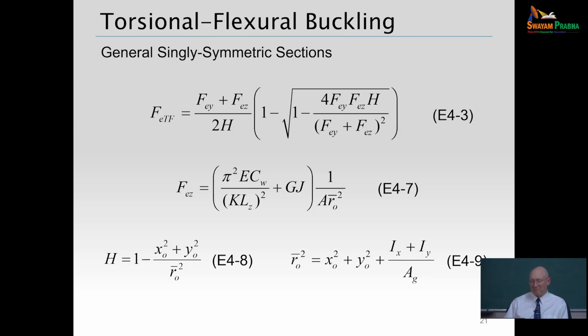We also have the FEY that's showing up there. It's kind of hard to glean it out from just looking at the equations, but if we start putting numbers in, what we find is that FE torsional flexural generally is going to be something smaller than both FEY and FEZ. And you can think about that conceptually, and similar to what I mentioned earlier.